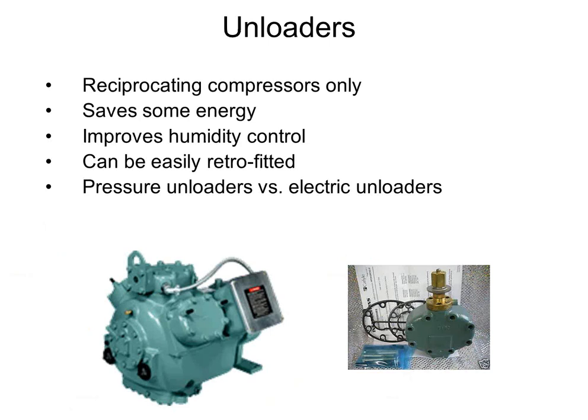Depending on the type of compressor you have, there may be things you can do to retrofit it. Now, we don't use a lot of reciprocating compressors anymore. In fact, we don't use them at all. But there are still lots of them out there in the field on larger units. A reciprocating compressor can have unloaders added to it in order to give it staging capacity. This is extremely easy to retrofit.